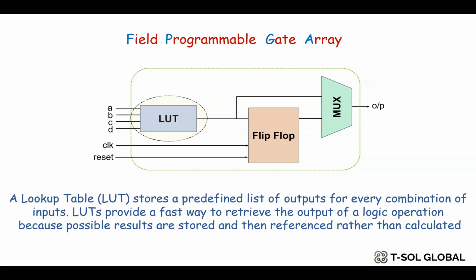So, an LUT carries a customized truth table for every possible input. The results are already stored, which gets loaded as the FPGA is powered up. It simply generates output based on the input combinations given by a user.